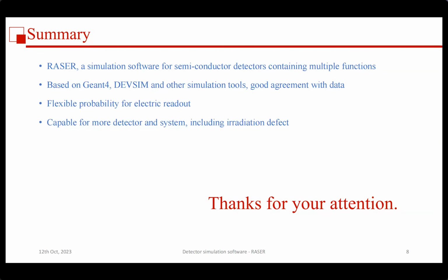Here is the summary. Hope you have some understanding of the simulation software RASER based on Geant4, DEVSIM, and other simulation tools. It can simulate multiple detectors and the results are reasonable. The electronic readout for users is very flexible. You can use experimental noise as input. Also, you can use ngSpice or some other tool to simulate the readout circuit. It's also capable of handling more detectors and systems, like irradiation defects for all of the semiconductor detectors.